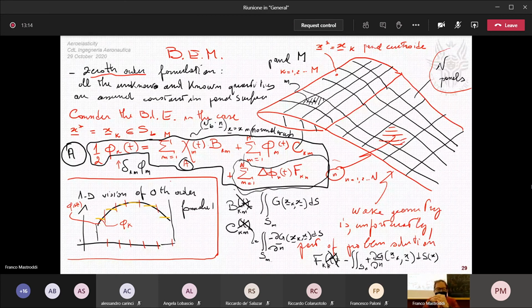First, yesterday, we proposed an algorithm for solving this original formulation within a nonlinear procedure. Essentially, we have divided the body surface in a number of panels, like M here, and the wake in a number of panels like N. This procedure is very popular and is also known as the boundary element method approach.